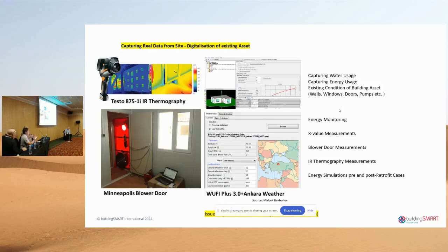If not just a building, in that case, we have a ceiling, right? We have to know what the material behind the ceiling is, what kind of membranes we have there, what the material of the timber ceiling is, and what the lambda values are, the thermal conductivity values. If we also have a chance to do building monitoring, but usually building energy monitoring is done within 1 year. We don't have such time, but we at least can do energy simulation. That's a more interesting case here.